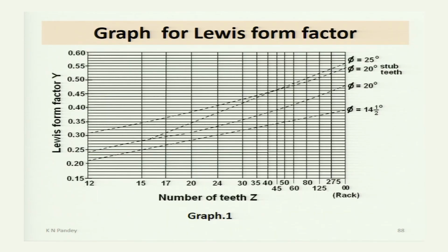This is a graphical way of determining the Lewis form factor. Knowing the number of teeth and the pressure angle, you can find the Lewis form factor.